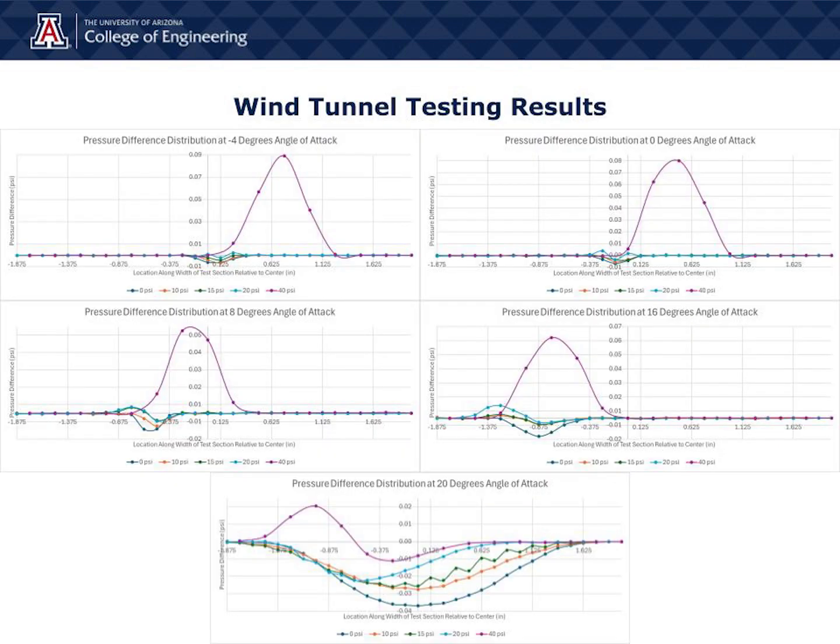The pressure deficit in the graphs is the region of the wake. A reduction of the wake can be seen at all injection pressures. The best reduction can be seen at 15 psi due to the reduction of the wake without introducing excessive pressure.